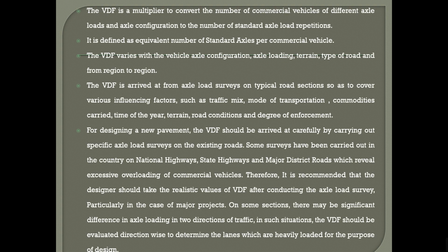Hence what we do is increase the axle configuration for all the automobiles, such that the load carrying capacity of those vehicles is increased, as we discussed in the ESWL concept as well as the EWL concept. With the increase in the number of wheels and the number of axles, the amount of load transferred upon the road is not going to be strained beyond 8 tons. It could carry 16 tons, 32 tons, as well as 64 tons, which is greater than the legal axle load of 8 tons. But how are we going to compensate that? By increasing the number of axles.